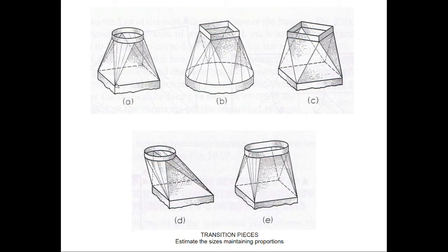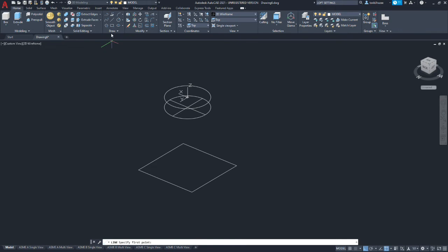So if we're to look at our PDF again, we have a triangular section going from the corner up to the arc and back down, where this is a flat plane. We need to create a curve that represents each one of these edges of the flat triangle section. So you're going to connect the corners, we can turn ortho off now, to the quadrant lines we just drew.